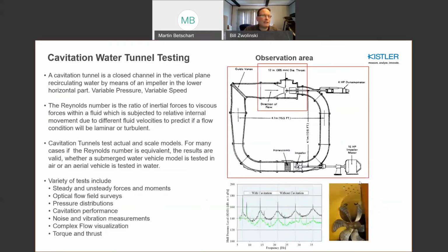You also have cavitation water tunnel testing, and in this case you might have a pressurized vessel that I mentioned before and some object under test. You have some dynamometer or maybe rope spinning that propeller shaft, for example, and you might want to evaluate cavitation, okay, with regard to pressure sensors being mounted in the vicinity of this propeller as it is operating.